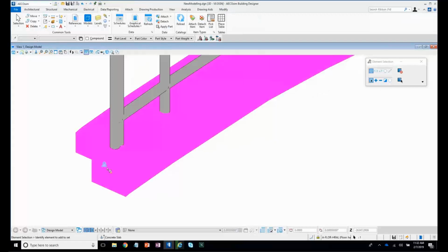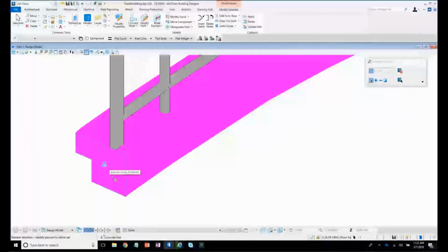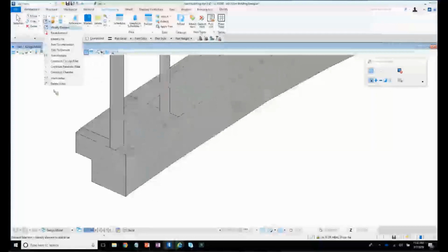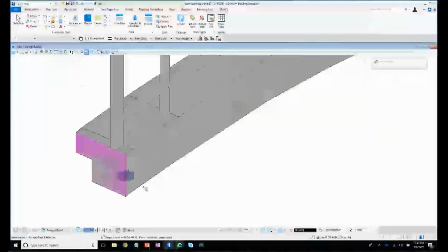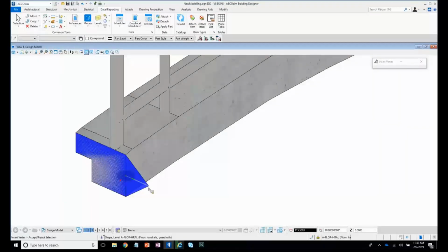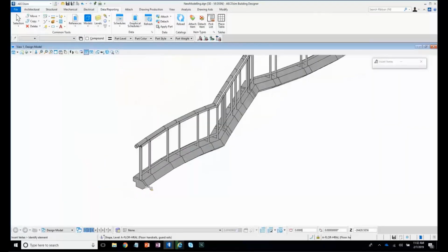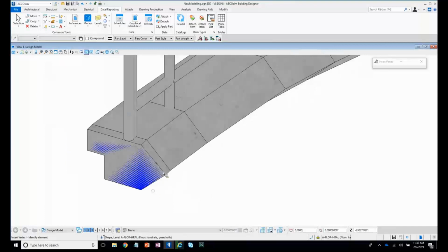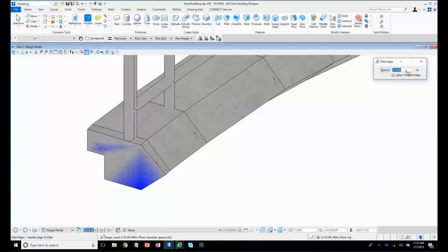If I wanted to get a little bit funky in the design, I can hold right-click down over the widget and say Show Input Element. What that will do is allow me to do some 2D operations on this. So for example, I could insert a vertex. If I pull that guy out like that, I can change the whole profile of the thing that we have here. It may be a case that I want to fillet this edge here. Now I could come back to my solid modeling tools here and use the fillet option and start to fillet the edges.